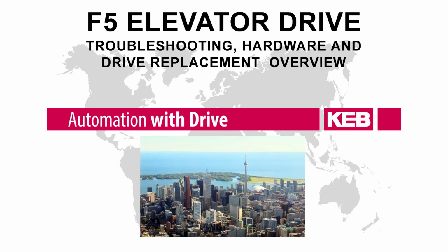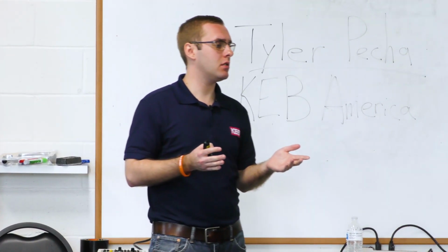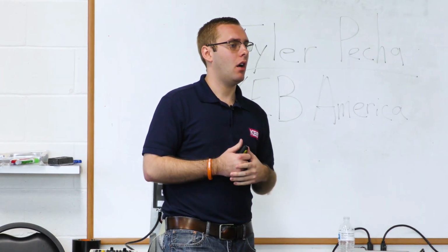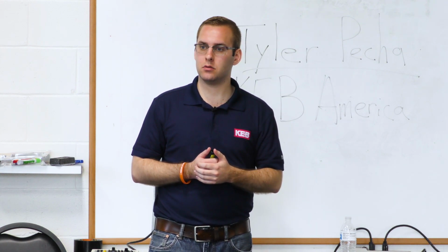Now we're going to go through some hardware troubleshooting. I did see that some of you have your meters here. That's good. On the drive, we should be able to tell if we have a bad input rectifier, a bad braking transistor, IGBT, that type of thing.